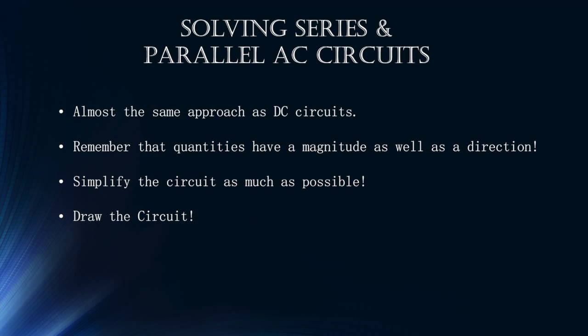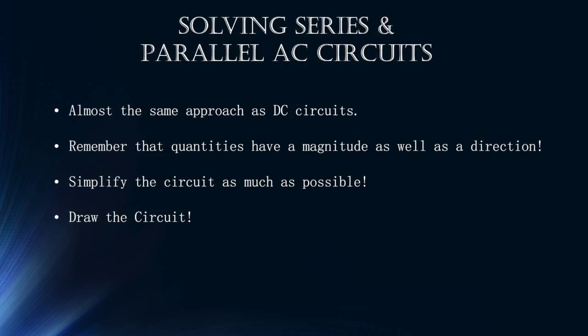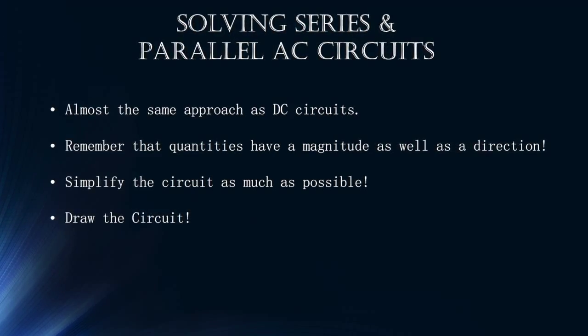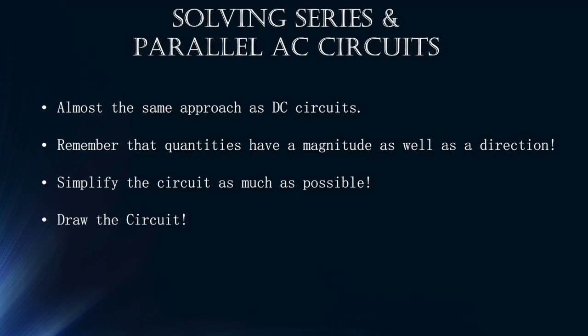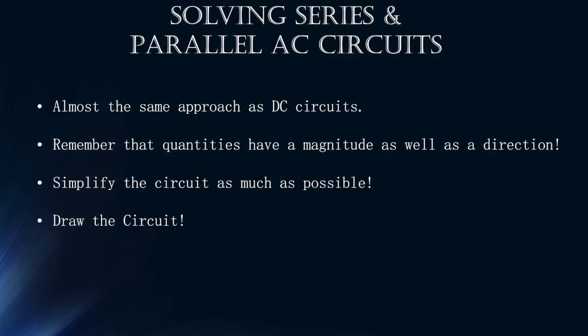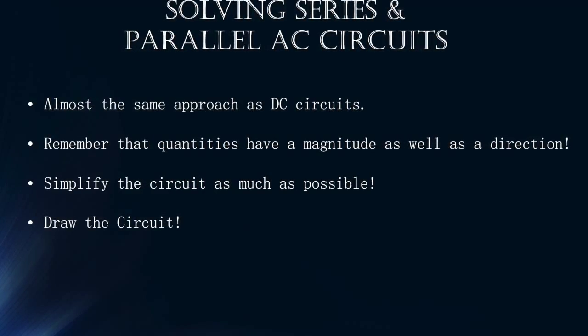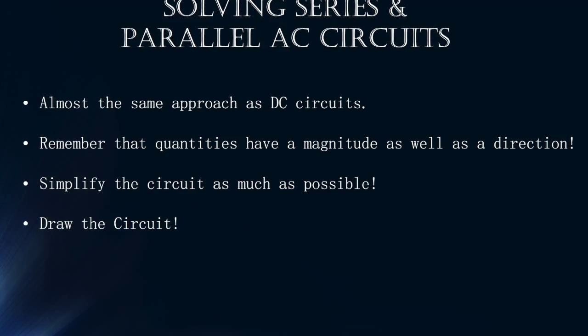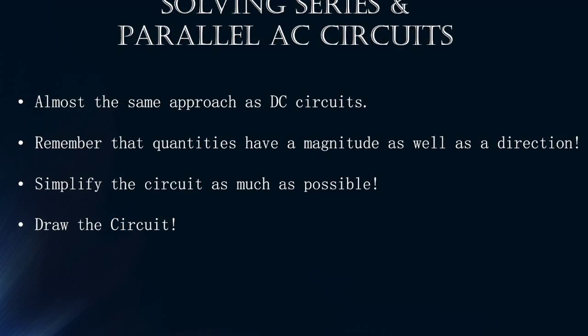Now, when it comes to solving series and parallel AC circuits, you can almost take the same approach as DC circuits. They can be solved through applications of Ohm's law, voltage and current divider rules, and Kirchhoff's laws. The only big difference being you are dealing with quantities that have a magnitude and a direction. It can be useful to simplify the circuits by making block impedances, and drawing the circuit always helps.